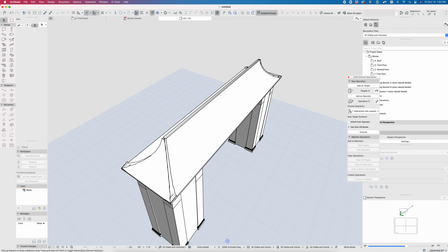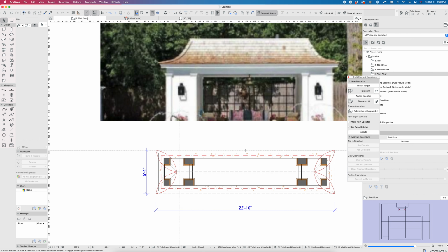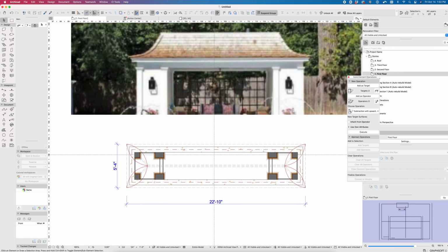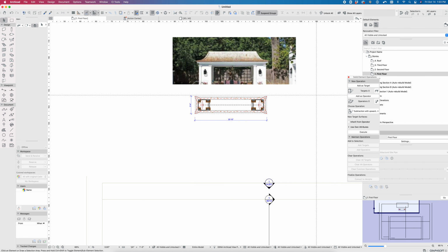There's got to be some resolution setting or some way to avoid that, or possibly another shell that just laps over that to represent these hip pieces coming through as well. But this is the general idea of how you can use these shells. Obviously there are also ways to get the morph tool to do this, possibly the object tool using the basic shape library under the special construction folder. But generally on shapes like this, swooping, curving, non-linear elements, the shell tool really is the best tool to look at for these types of things.